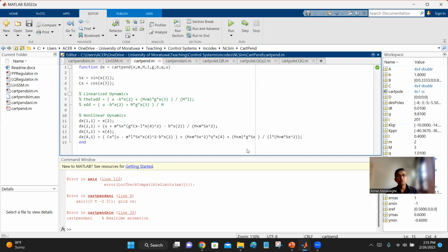So you can run it for T span, the total simulation time. When you run this discrete simulation, from rate of change to the next state and so on, you better use built-in MATLAB functions like ODE45 rather than writing your own, to make it more accurate.